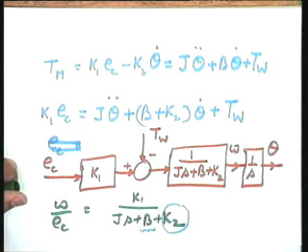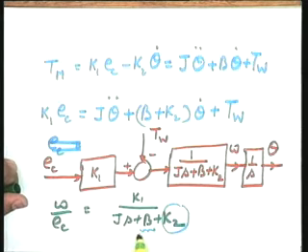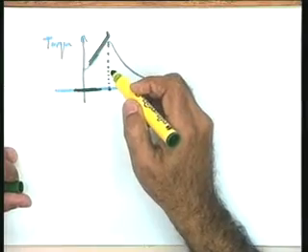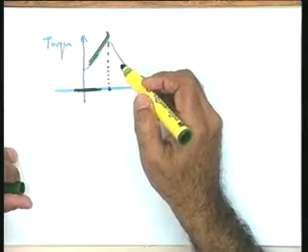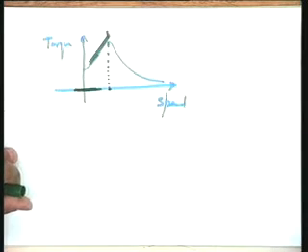Too many oscillations will naturally come, and it can even lead to instability because of this damping, because K2 has a negative sign. Now it depends on what the net damping is, which depends upon the magnitude of B. The B value has to be extremely high to take care of this negative damping effect, and it is for this reason that this characteristic is never allowed in servo applications, and hence an ordinary induction motor cannot be used for servo applications.